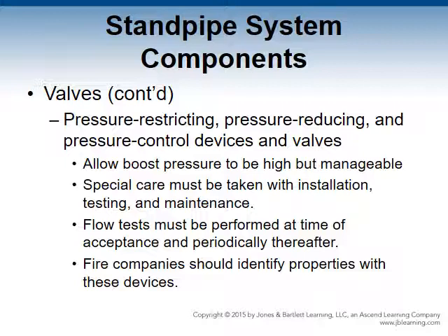In the past, these devices have sometimes failed to perform, so it is necessary to perform a flow test at the time of acceptance and periodically thereafter. Merely verifying that the device operates is not sufficient. Flow rate and inlet-outlet pressures need to be verified as well.